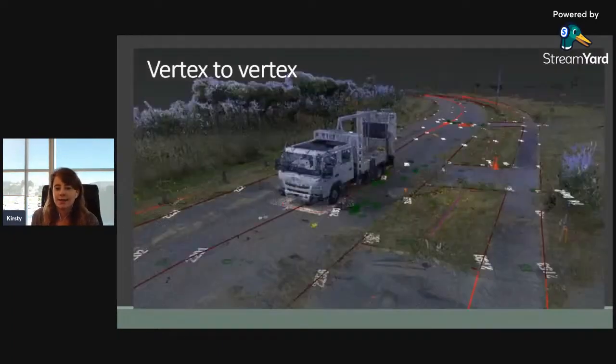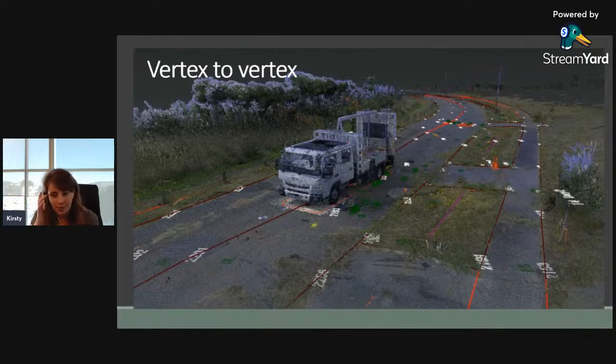So here I've got that data set from before where I just overlaid the information from the total station. And that was quite good. Just go through different areas and see how it comes together across the point cloud. So it's not affecting your registration. It's just a good overlay. So if you're out there collecting points for your data, just going out and picking out some extra features and overlaying them is a good way to add extra checks to your data.